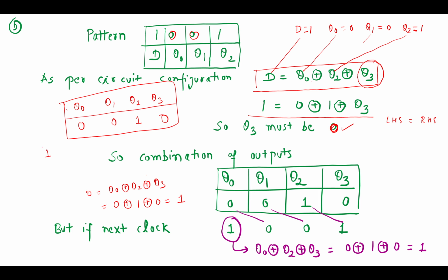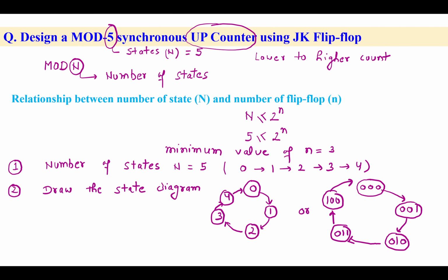So in the first clock, this is your data. D value is 1. This 1 comes here into Q0, and now the shifting of data starts on the right side. So after one clock, the data in all the flip-flops is 1001. That is the final answer. Okay, fine. Now we come to the next question.